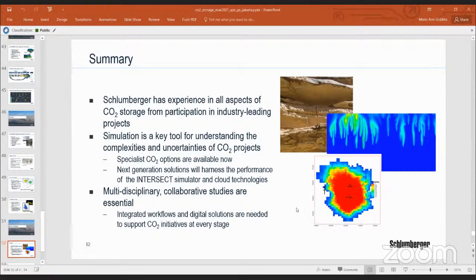You mentioned earlier that CO2 brine density becomes denser as CO2 dissolves in the brine. Does this phenomenon apply the same way in CO2 oil density, as we know that CO2 will swell the oil? Yes, so certainly any molecules which are less dense than CO2, CO2 is quite a heavy molecule because it has oxygen in it instead of just hydrogen. So it can have density effects on any other fluid that it's dissolved or mixed with.